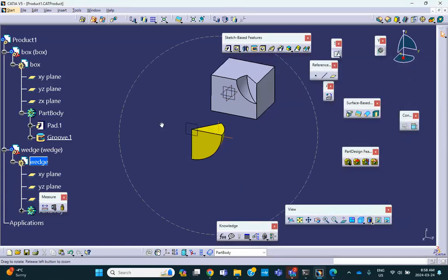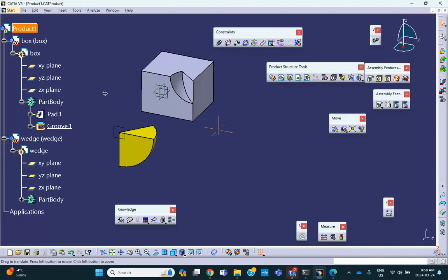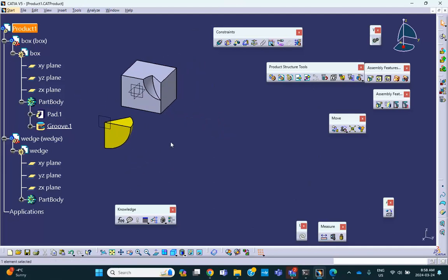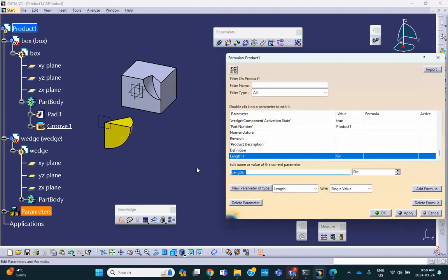Good. So all the way to the top. Now we're going to introduce our parameters. This is at the top level. So go to f of x, new parameter. This is length. One of them is going to be L. And nominal value. If you want to see the nominal value, click on the product. You see roughly 2.48. I'll make it 3.